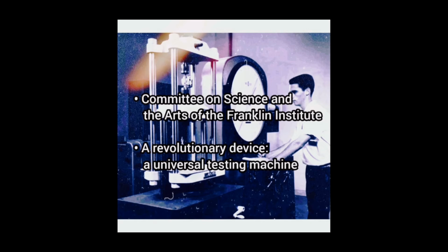In his patent application, Olsen explained that testing machines previously had difficulty measuring the pressure on the sample or wasted most of the applied power in friction. He proposed to build the weighing levers to be more compact, decrease the power absorbed by friction, provide an automatic motion for the weight on the beam, and provide a sensitive measuring apparatus for measuring the distortion of the specimen, as well as an apparatus for graphically recording and illustrating the same distortion.